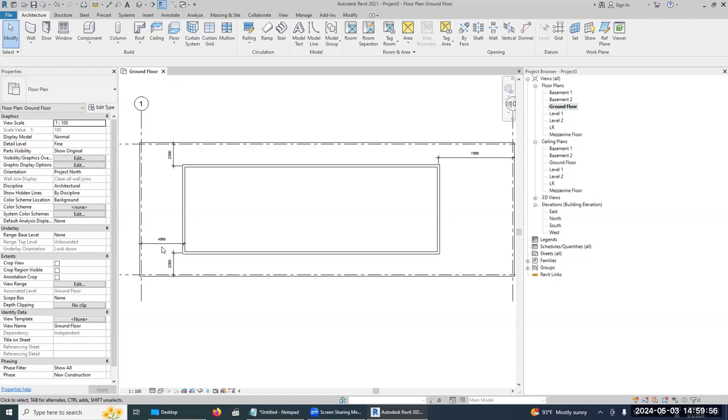Change this dimension first. Go down. This is 2,000 only. Select the wall and click 2,000. Enter. And select the second one. It is also how much? 2,000. Okay, select this one. Change 4,000. And do this one for this. Here. How much is? Select the wall. 7,000. Enter. And that's it. 3D.